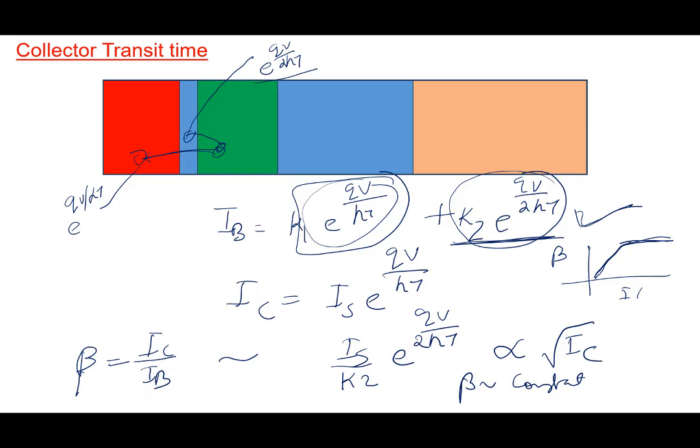So at least you're getting an explanation for one segment, the initial rising segment. Why is gain rising with current density? Mainly because when you see that phenomenon, current gain rising with current density, what is happening is that base current is coming because of the depletion region.